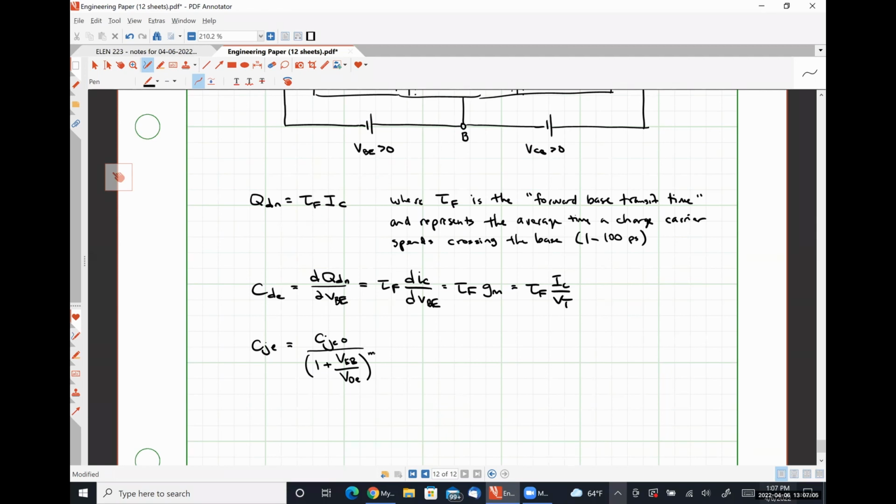To the nth power, which I believe, I don't remember if we talked about linearly graded versus step graded junctions in 335 or not. We might have just thrown all of that under square root and moved along. Do you guys remember? Okay, so effectively all M depends on is what type of junction we have. For a step junction, M is 1/2, and for a linearly graded junction, M is 1/3, which is how this winds up being the exact same equation we had before.